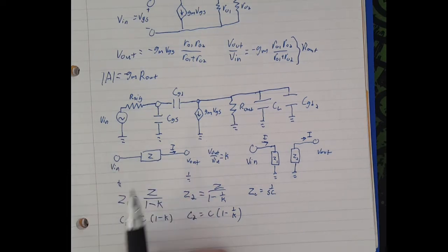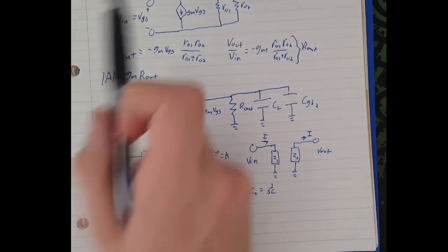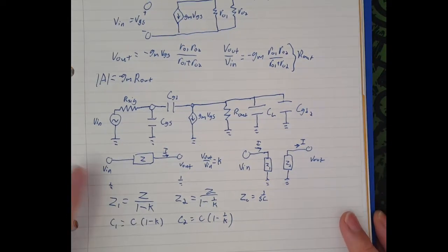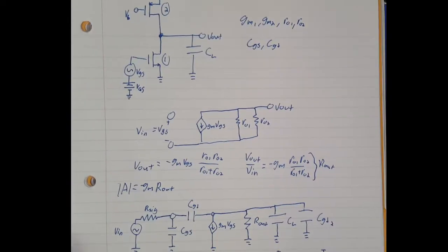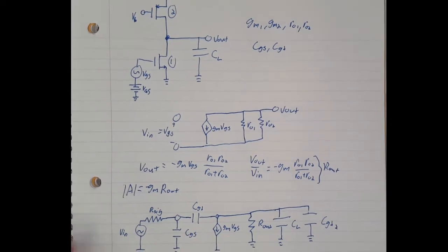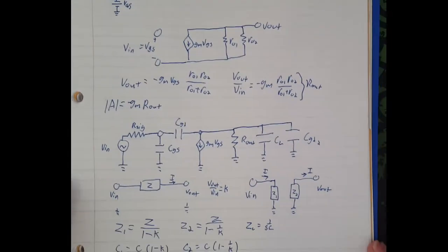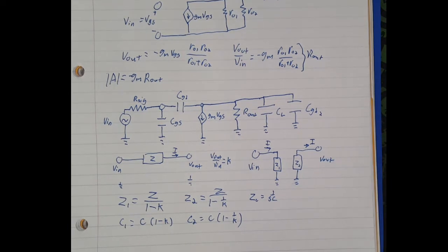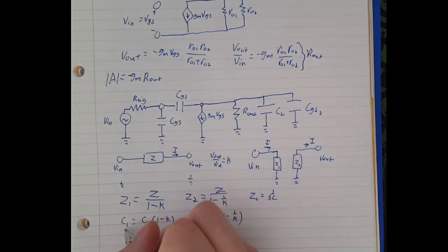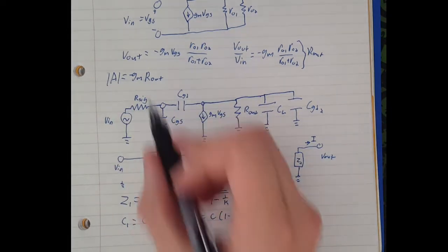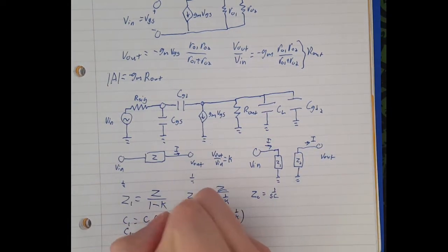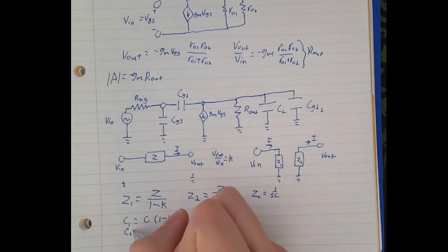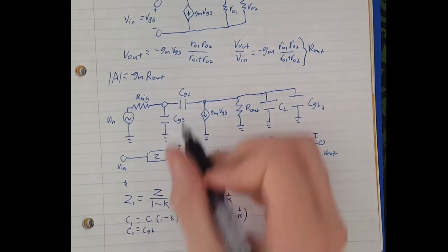Now, we can assume this to be large because the gain from common source amplifiers is typically very large, usually at least 100. You're usually going from millivolts, microvolts to millivolts, or something on the scale like that. So we can simplify this out, and this is negative, so we'll just plug this in here. C1 here is equal to CGD, because that's the one we're splitting,